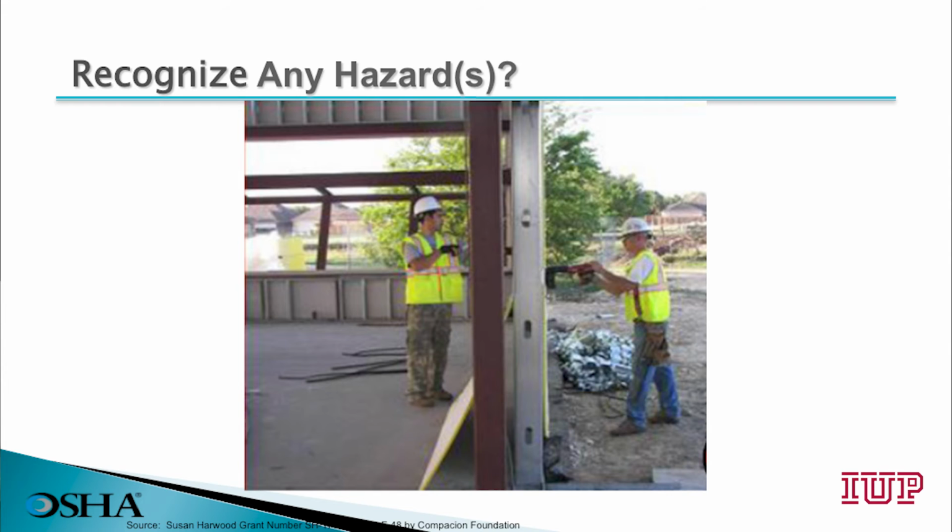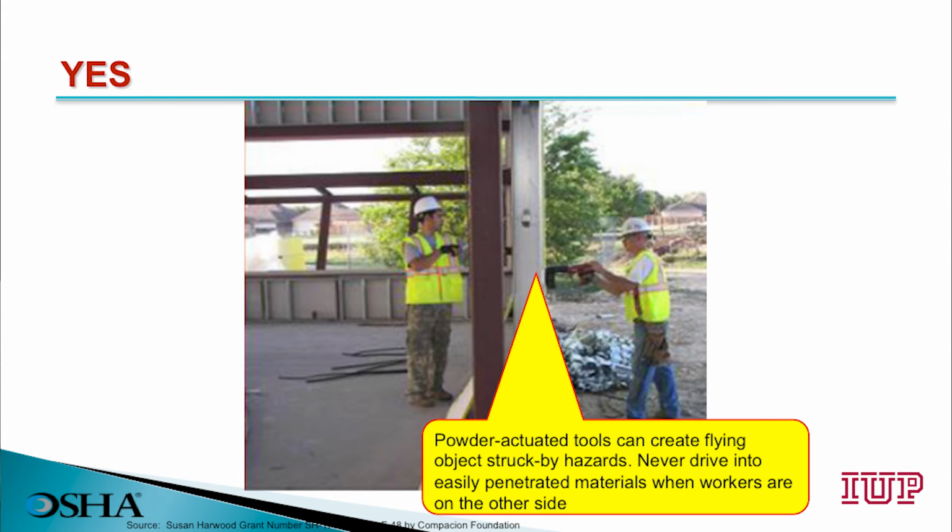Do you recognize any hazards? Powder-actuated tools can create flying objects struck by hazards. Never drive into easily penetrated materials when any workers are on the other side.